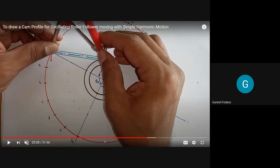You can see now roller center is on prime circle. So we have to mark that position of the roller center on a prime circle. And for drawing position of roller center on a prime circle, we will take distance equal to length of the follower arm, which is 7.6. So by taking distance equal to 7.6, center as A, B, C, D, E, F, mark arcs on prime circle. I repeat, with distance equal to length of the follower arm and center as A, B, C, D, E, F on a fulcrum circle, cut arcs on a prime circle to get position of roller or position of follower at every position. Let's see it.